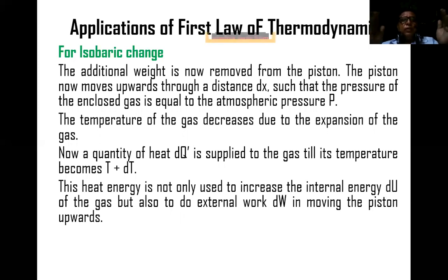The additional weight, which we applied in the isochoric case, is now removed from the piston. The piston now moves in the upward direction with displacement dx, such that the pressure of the enclosed gas is equal to atmospheric pressure P. The temperature of the gas decreases due to expansion of the gas.